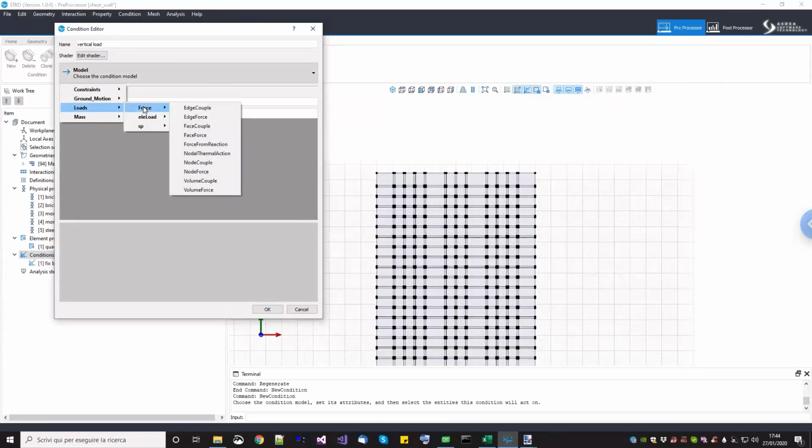Now, as you know, in OpenSees, you either have distributed load only under the command eleLoad. But unfortunately, this command is only available for beams. And in this case, we are not using beams, we are using continuum elements. So what we have in OpenSees actually is just plain nodal loads. But fortunately, in STKO, we created some automations. As you can see here, you have edge force or face force.